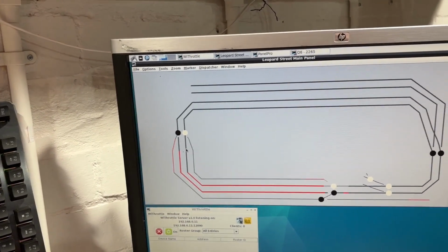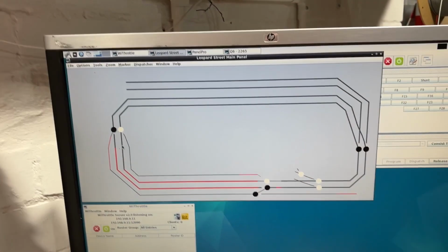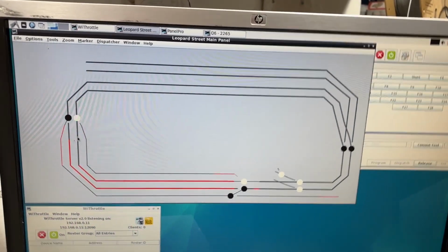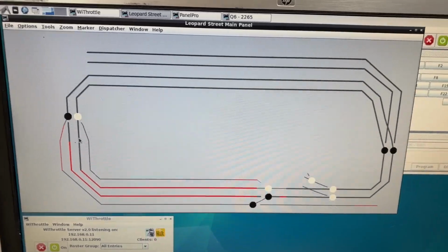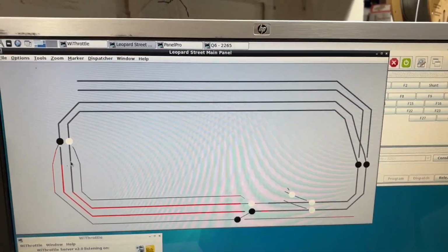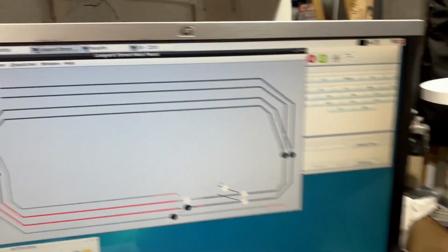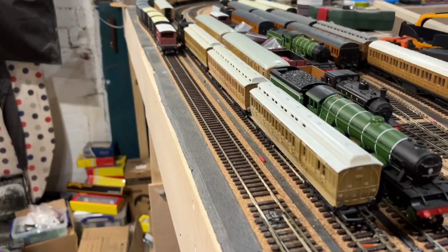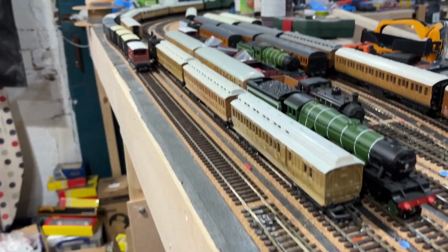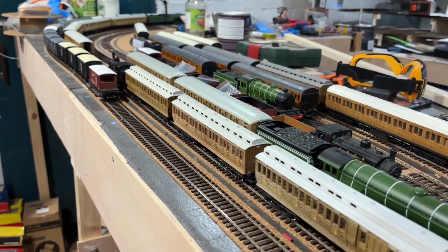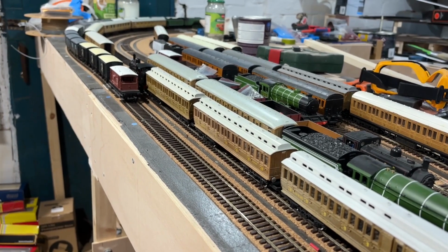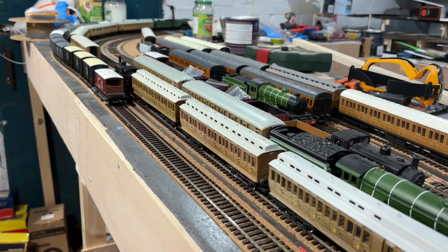Message Queuing Telemetry Transport. It's a simple piece of software, a broker upstairs, a little server. The ESP publishes a message to it, and it has a message for each of the virtual switches. And it says, this is where my switches are, this is what this thing looks like. And it doesn't do a great deal with it after that.